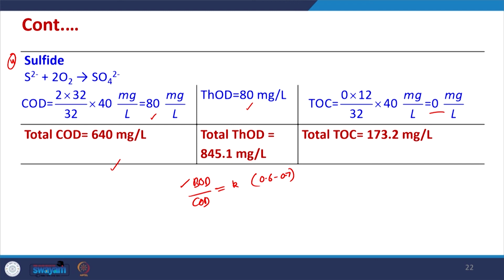beforehand, before actually doing the test, or also these methods can be used for performing the calibrations of our systems. So, we should periodically cross check. We can add these types of compounds in our usual system of determining the COD, THOD or TOC, and through that we can perform the calibration and cross check whether our system or our method is working properly or not.